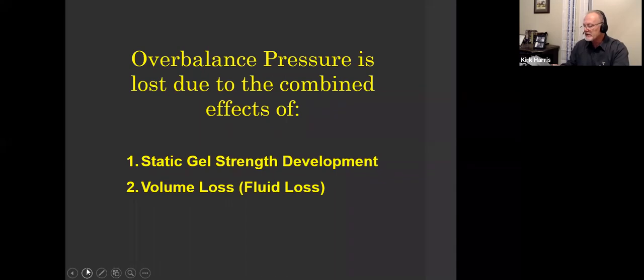The industry has conservatively adopted the upper end of the range as the accepted limit. In other words, at 500 pounds per 100 square feet, the industry has accepted that bubbles will not freely percolate. We can mistake this to say at 500, gas can't flow through cement at 500 pounds. It doesn't say that. It says cannot freely percolate.